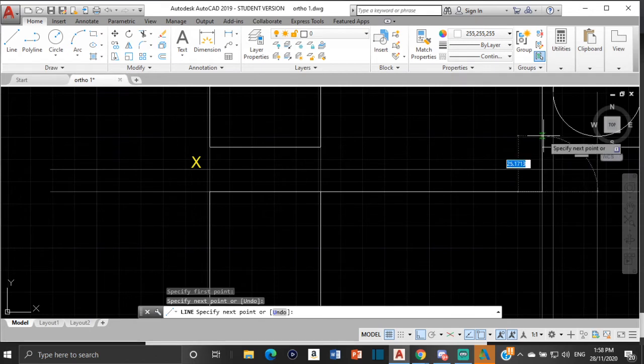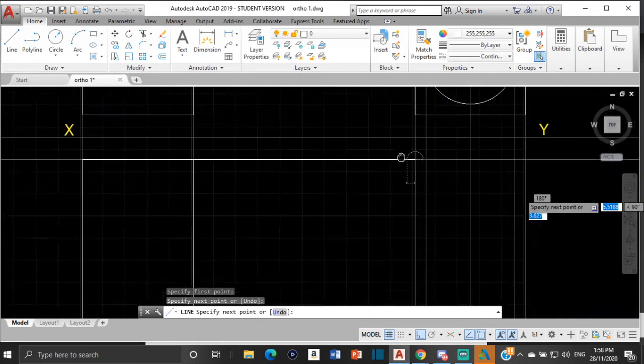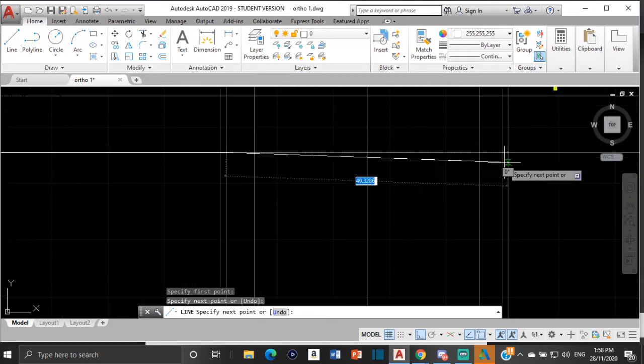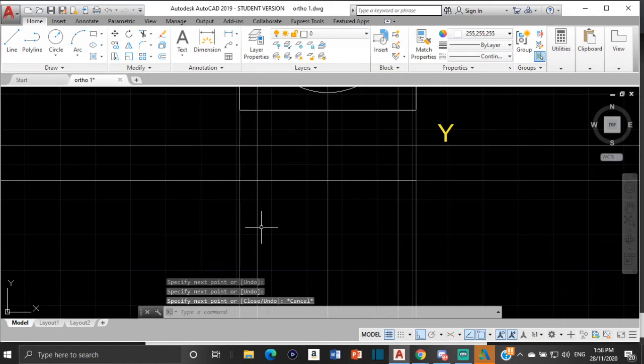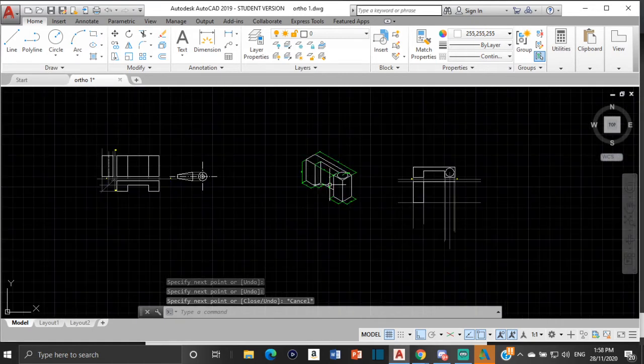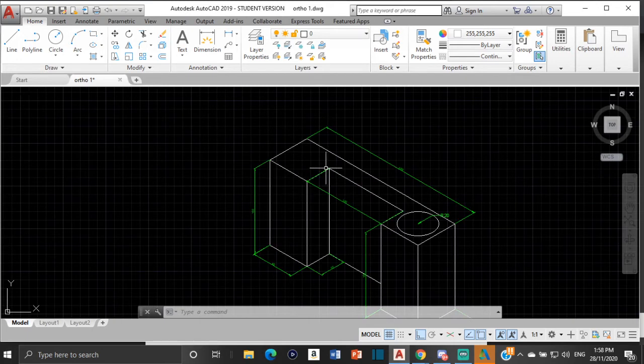And that line represents this edge here. Actually, it would go all the way across, and I'm going to tell you why. It would go all the way across to there. Why does it go all the way across to there? Because when we're looking from this direction, we're going to see this line here. We're going to see that line, and that line, but they're going to look like one flat line going across, like one straight line going across when you're looking from the front of this figure.